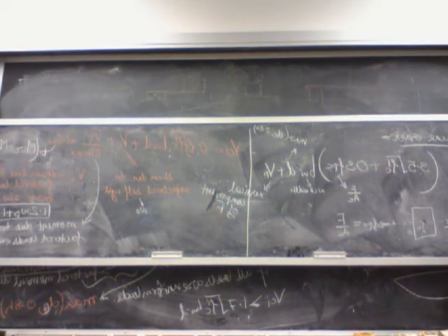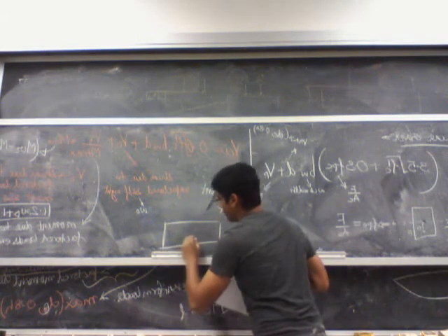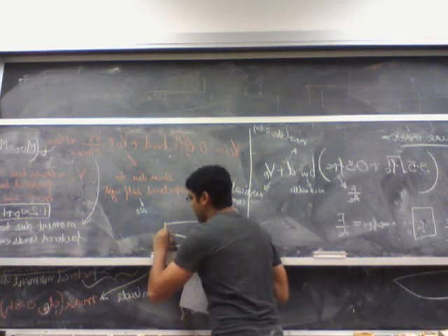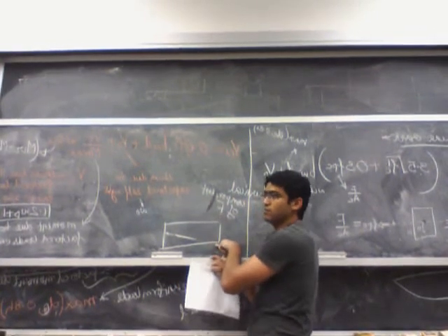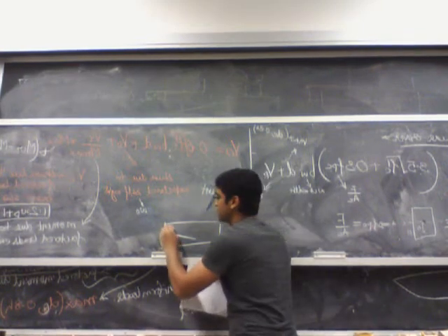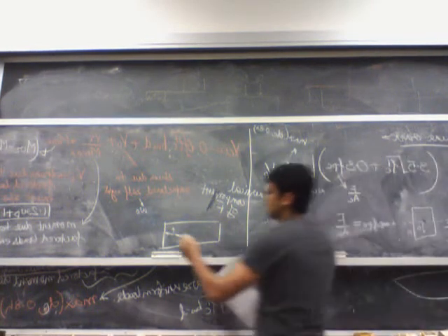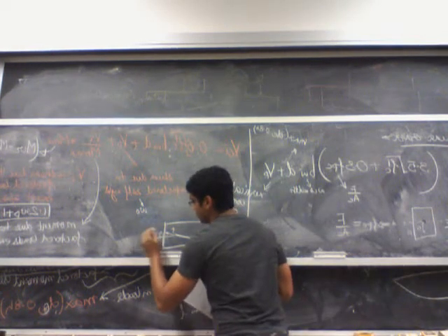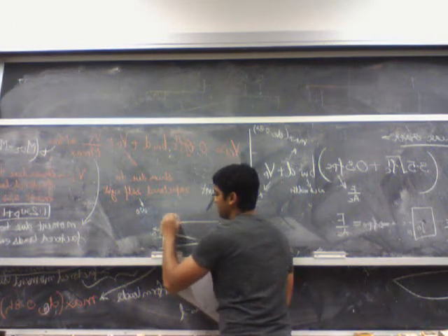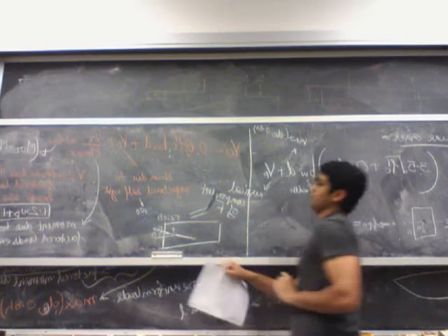So if your tendon is actually draped, if it's not a straight tendon, if my tendon has any angle to it, then technically my pre-stressing force is acting along the tendon itself. So if my tendon is at a certain angle, I have some vertical component to that force F. If this angle is theta and this pre-stressing force is F, then the vertical component is F times sine of theta, and that is actually my VP.